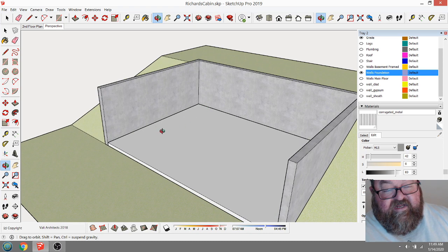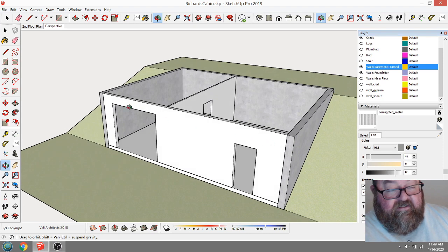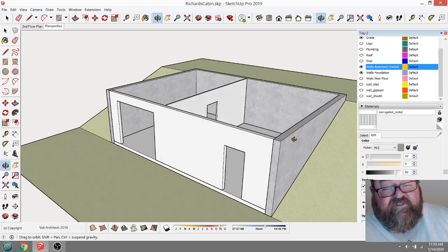But one of the advantages of having this situation where one side is open or daylighted is that we can frame up this wall, which is less expensive. A framed wall with siding on it is less expensive than trying to pour this wall out of concrete and trying to form up these headers. That's the expensive part, the labor of forming these openings in a concrete wall. Plus just the system itself is more expensive.